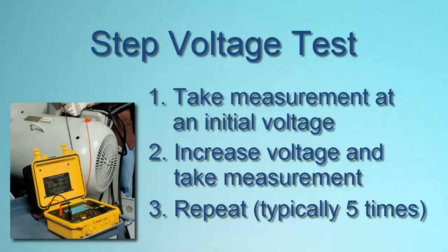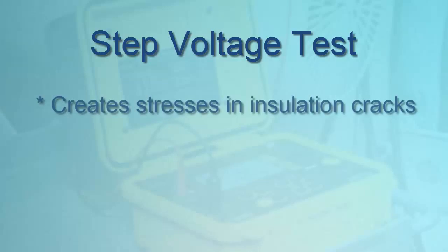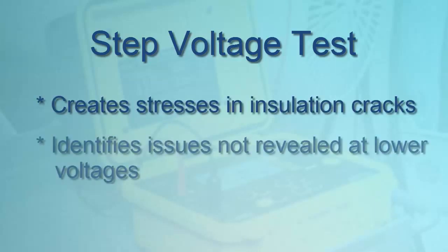A common practice is to test at 5 voltage steps. The step voltage test is designed to create electrical stresses on internal insulation cracks, identifying potential problems that may not be revealed by testing at lower voltages.